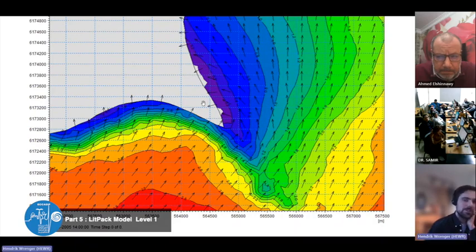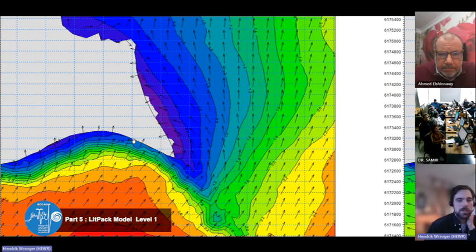The only alternative is to do a two-dimensional modeling, which also has its limitations because it's computationally heavy. Then maybe you can't run 10 years, and also it might not be justified compared to the other uncertainties that we have anyway. For example, we don't have high-resolution bathymetry data available. We only have 3 locations of sediment samples. So it is okay to have slight inaccuracies as long as we are aware of them.